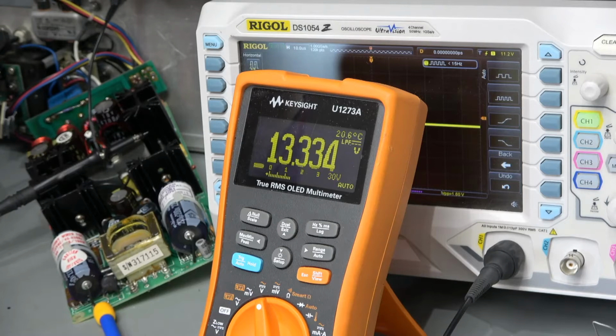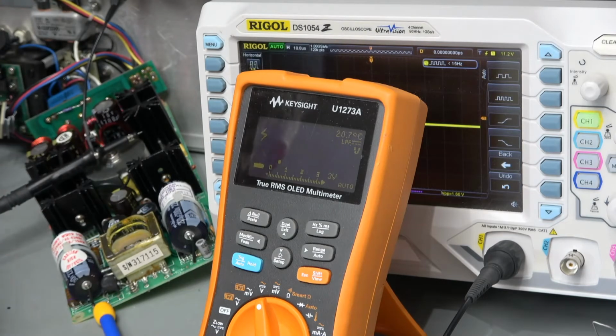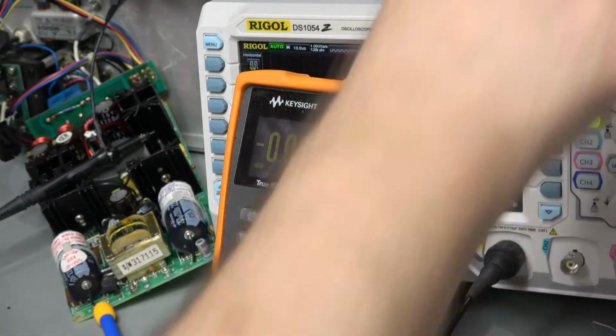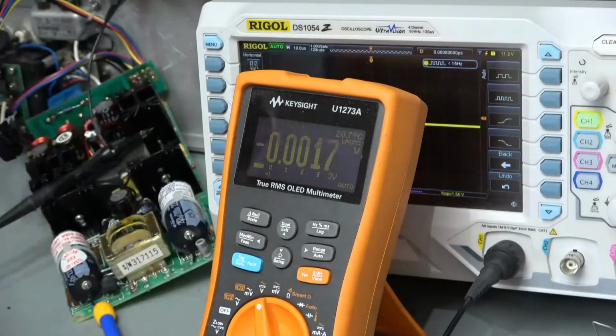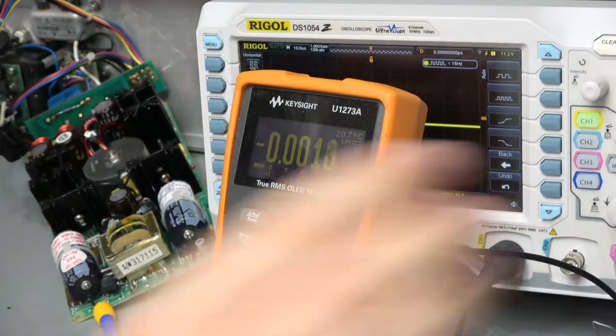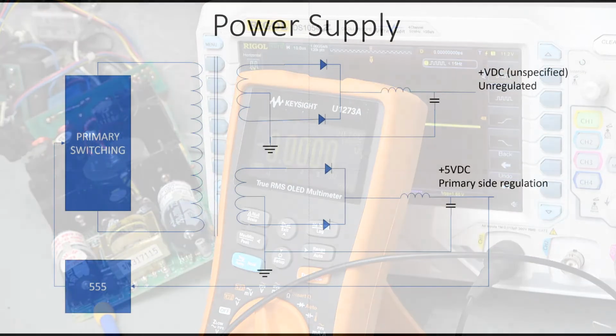but they just grow forever. Now on the newer one, what happens is we get our 5 volts DC regulated, absolutely fine, but the plus minus volts DC, unspecified amount, is less than a volt. So, you know, something is happening somewhat different there. Now, when I put it under load, the new one works. It gives us an expected type of voltage, and it's stable and set, and everything is absolutely fine. So what is the difference?